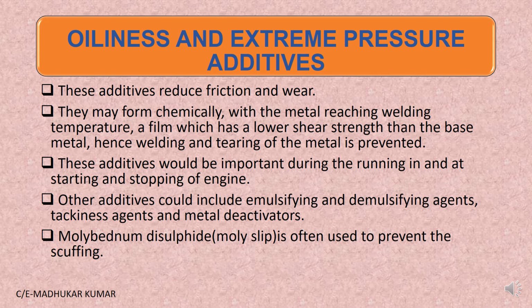They increase and improve the load carrying capacity or the pressure tendency. These additives are important during the running in and in the starting and stopping of the engine, because at the starting and stopping time, the friction is more. And running in also, I hope all of you know what running in is. So in the running in process also, these additives play an important part.